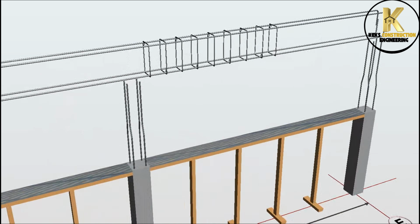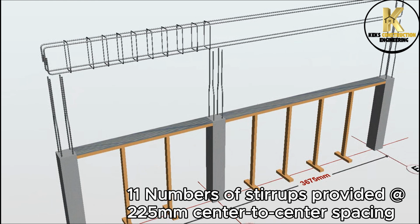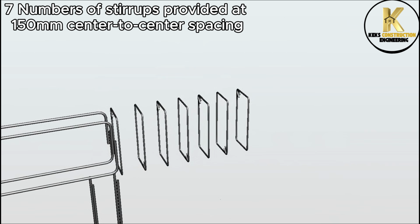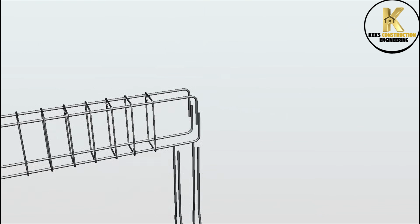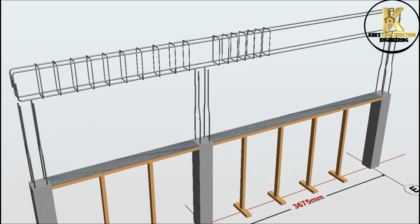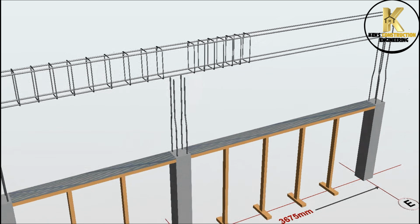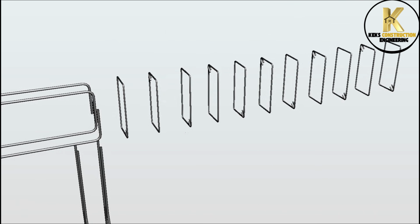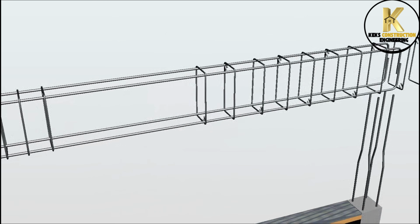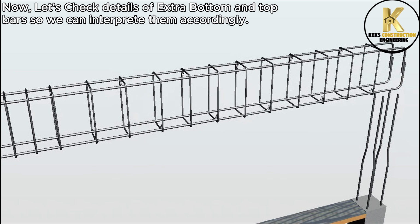10 numbers of stirrups provided at 225 mm center-to-center spacing. 7 numbers of stirrups provided at 150 mm center-to-center spacing. As you can see, the stirrups at support C are placed closer to each other at 150 mm center-to-center compared to the stirrups at the span. This is to resist maximum shear force at the support. 11 numbers of stirrups provided at 225 mm center-to-center spacing.